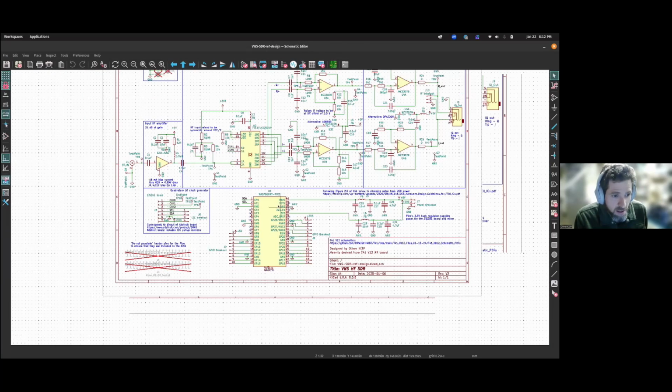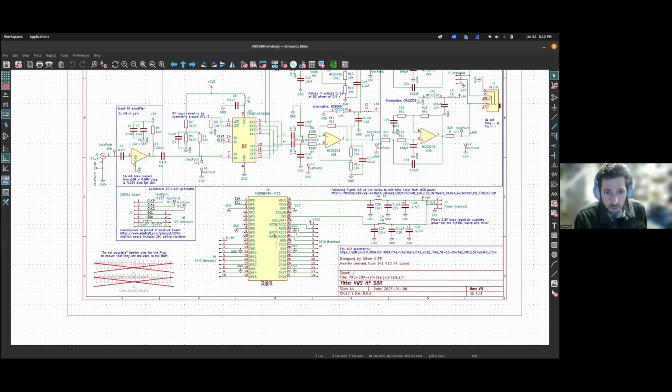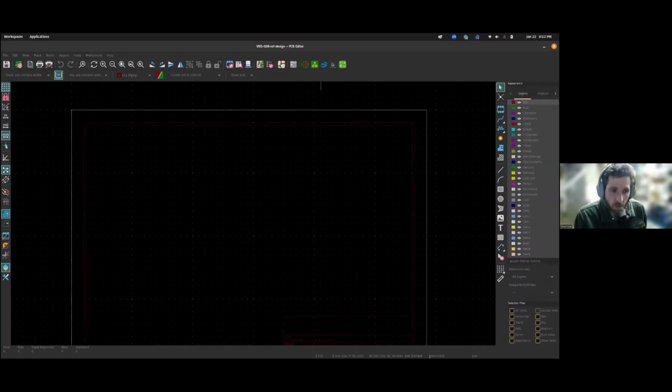You recall from our schematic, we will have a microcontroller board, the Raspberry Pico, on the same PCB as our RF electronics. So we've got this mixture of RF and digital signals. In a case like that, you're best going for a 4-layer board because that helps you to maintain isolation between your digital and your analog domains and reduce crosstalk between traces.